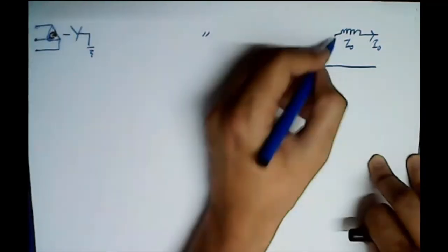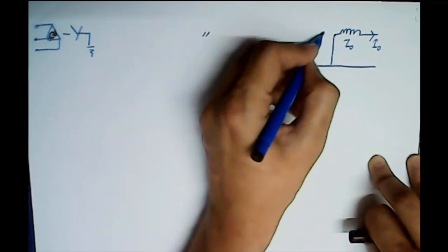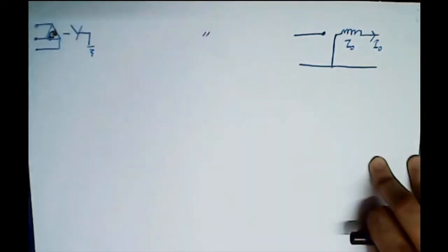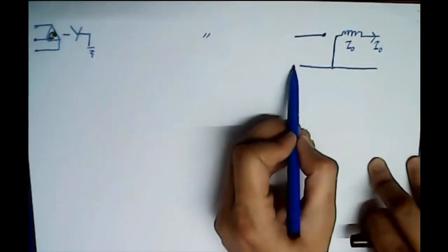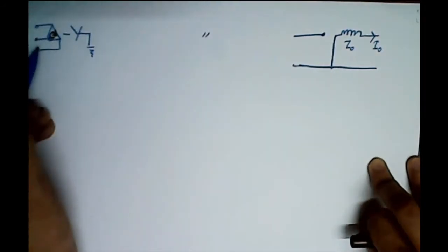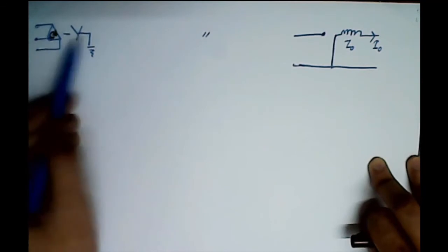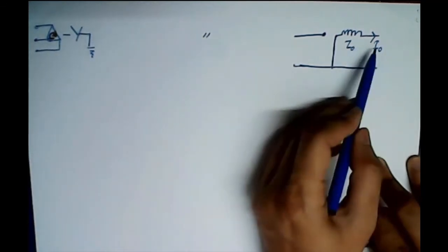But if there is a current circulating within the delta, this means that the balance will be maintained, and therefore we say that zero sequence current can flow at the secondary side but cannot flow at the primary side. Why? Because the delta lines cannot carry this zero sequence current, but the delta winding can carry circulating current to balance this secondary zero sequence current.